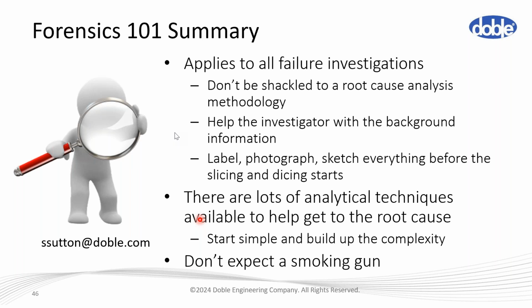So in principle, we can perform PD testing on any type of cable. It tends to be applied more frequently to solid dielectric cables, EPR, XLPE, less so to oil-filled cables, because to get PD, we need some form of void. And if you have an oil-filled cable, the oil naturally tends to flow back in and fill up a void.